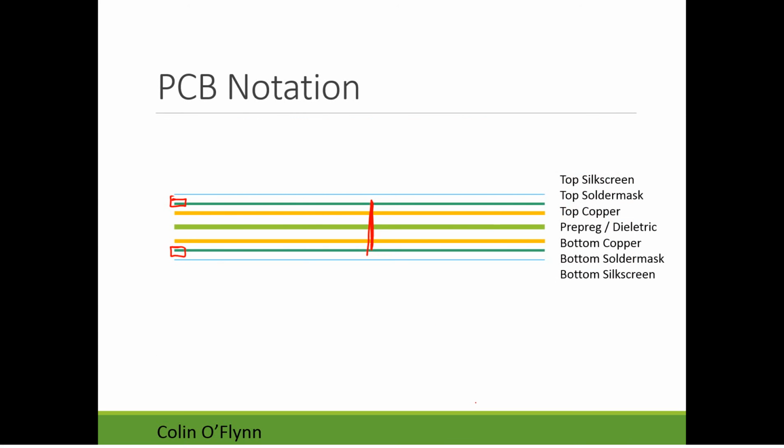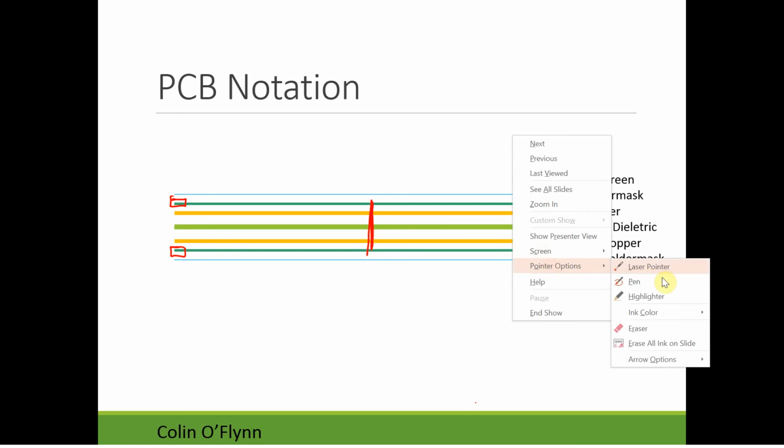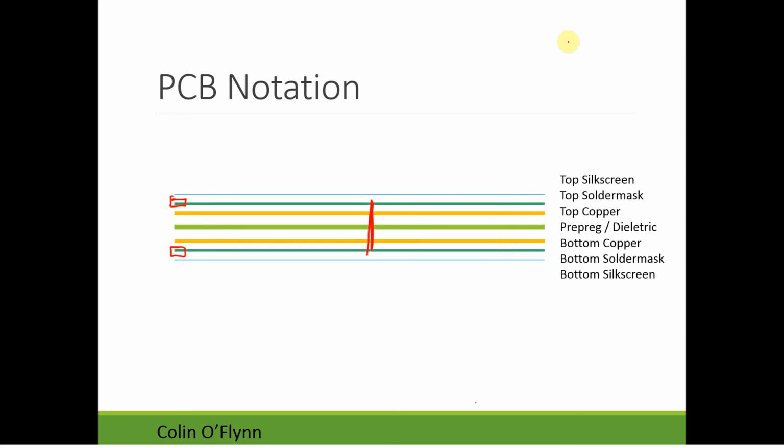When we look at what's known as the stack up of the board, those names I used before appear again. The Silkscreen is this very top layer, and this again was just whatever material I wanted to write about the circuit board on it. The solder mask is put right on top of that conductive top layer, which is copper, normally coated with something, so it's either immersion gold coated, or coated with tin, or coated with solder, which could be lead or lead-free, depending. So some sort of top coating on top of the copper.